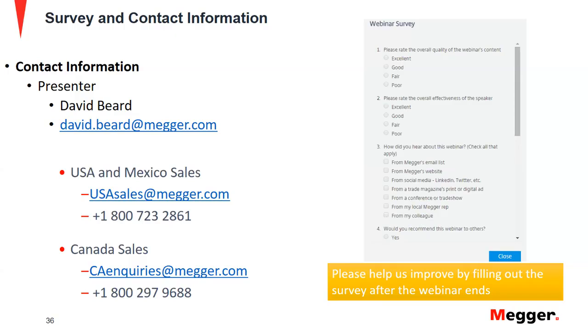if it's plugging into a panel using a test switch and going up. We do have a meter function inside RTMS as well. It allows us to put in a current, voltage, and some angle on each individual phase, and then it'll go through and calculate whether the applied values compared to the measured values are correct or not. That gives us a quick wiring check. I hope that's what I'm answering. If not, again, leave us some information. We have email, we have a survey. That way we can better answer the question as well. But hopefully that gave you an overall idea.